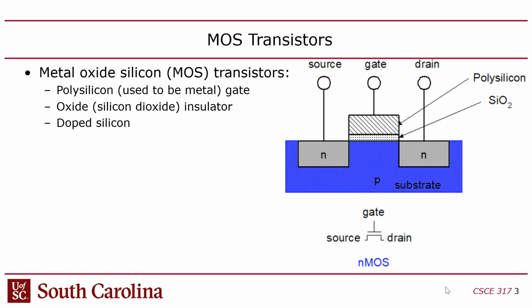So all you've got to do is keep the substrate grounded. As long as this has a lower voltage than the diffusion area, then they're basically not connected, even though they're right up against one another. They're not electrically connected, right? There's no connectivity there between those two. You guys with me? So you have these two diffusion areas, and in between the two diffusion areas is a